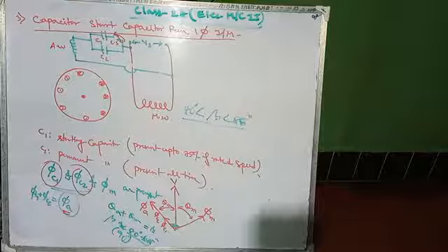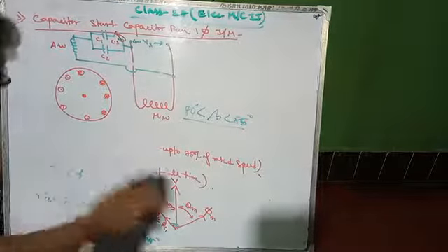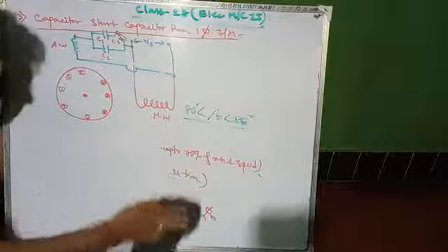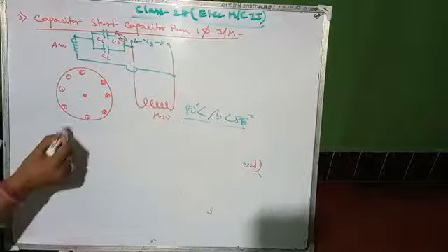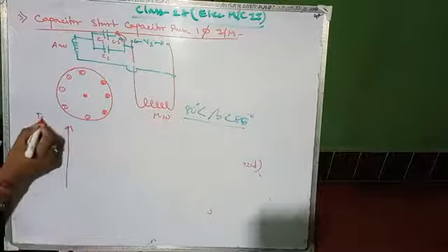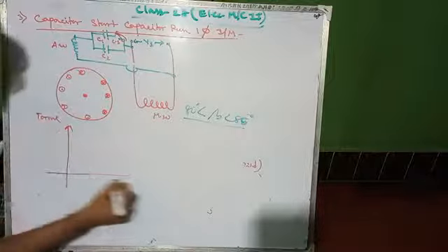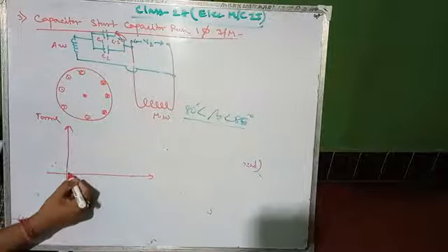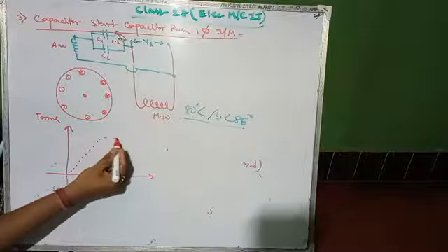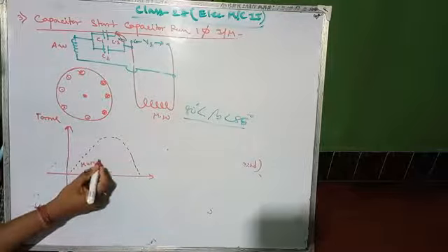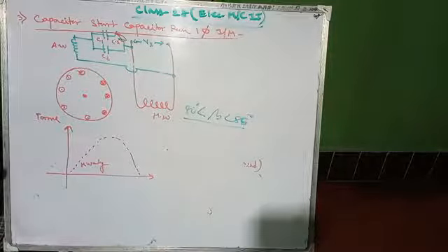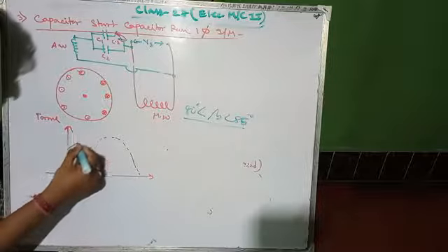The starting characteristics will be similar to those of the capacitor split phase induction motor. Suppose we are taking torque. When it is the main winding only, the characteristics will look like this. When it is main winding plus C1 plus C2, it will be enhanced.